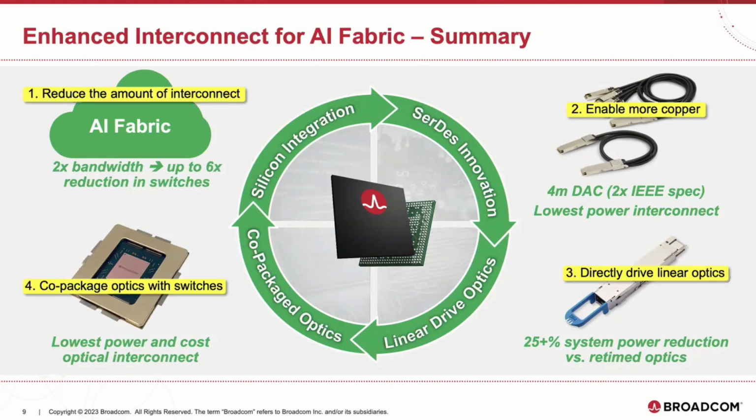The key thing here is that the SerDes that we have, starting with our 5 nanometer generation, is natively capable of supporting DAC, linear drive optics, those LPOs, and CPO. So if we decide at some point we want to take any switch chip, any product that uses that 100 gig SerDes, and add CPO to it, it's really just a packaging exercise. All the chips natively can support the high reach DAC, LPO, and CPO.